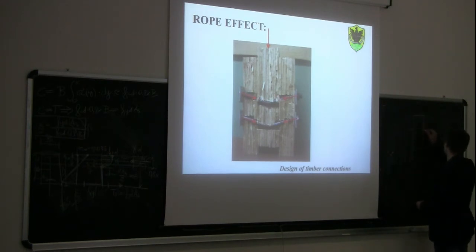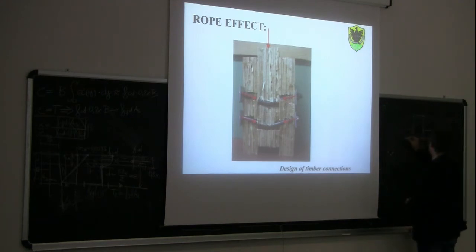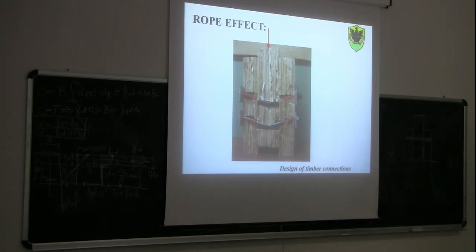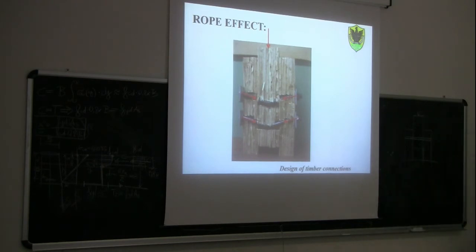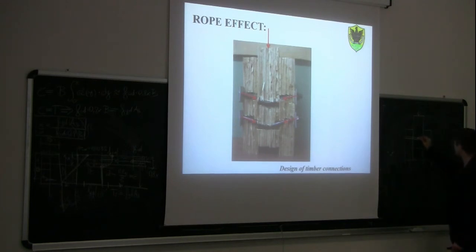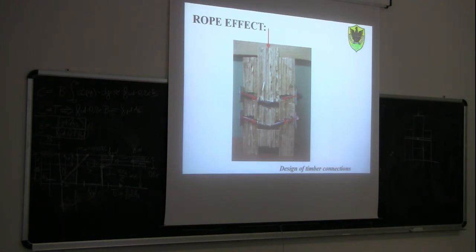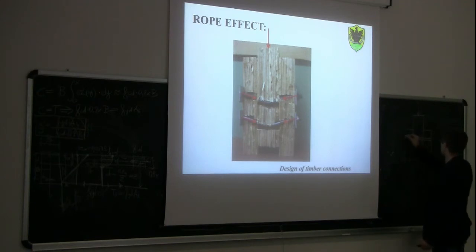And this is the dowel, initially straight, without any washer. If I push down the specimen, what kind of deformation can I expect? Assuming that there would be a plasticization of the dowel in the central part, I can expect this is going down, and this is going to deform this way. Right? Is it reasonable?